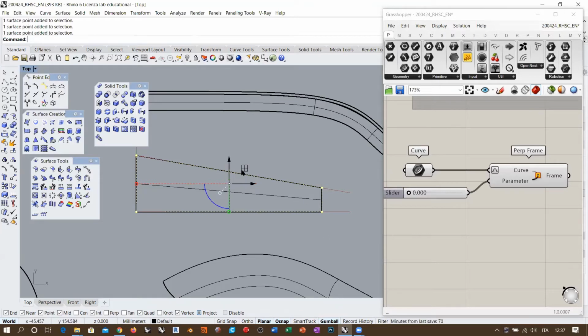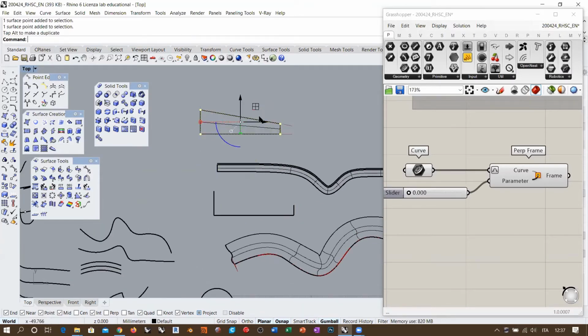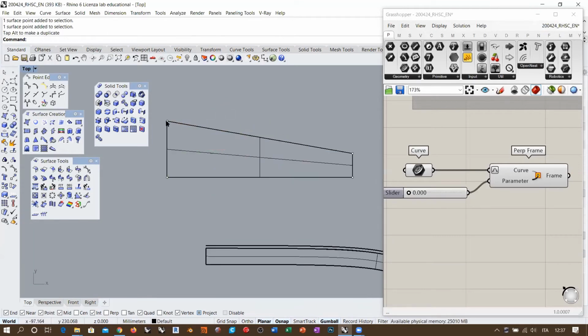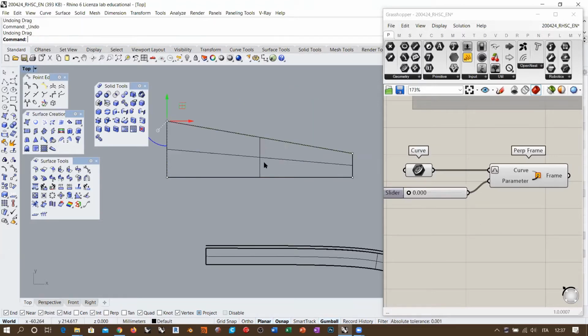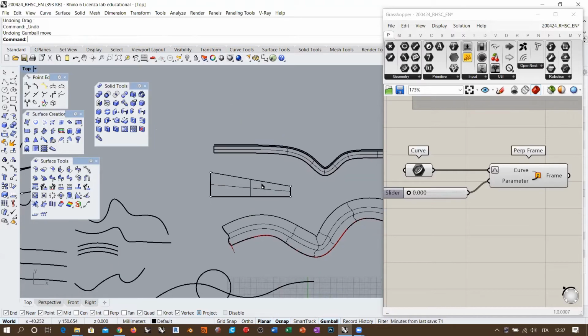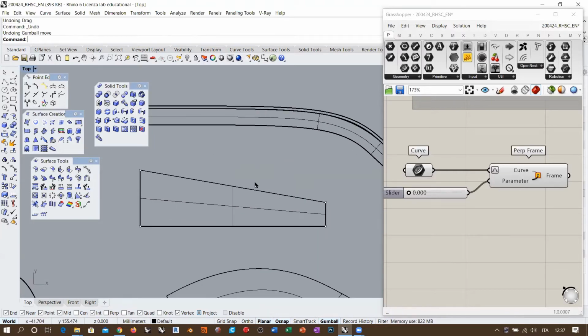I got the simplest possible surface, which is a 4-sided bilinear surface, so there is no possibility of deforming this surface internally. And this is curious, because if the loft creates a third-degree interpolation, the sweep doesn't, and it's more complex than the loft. So this is something that I wanted to point out.